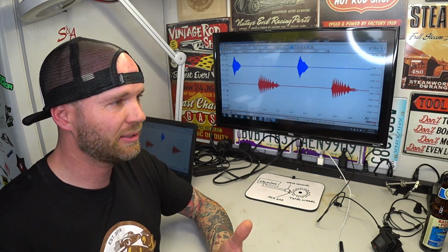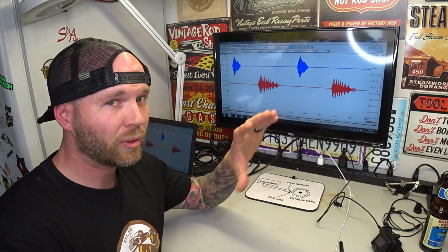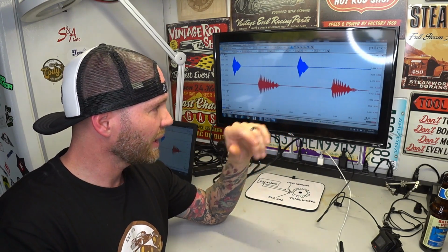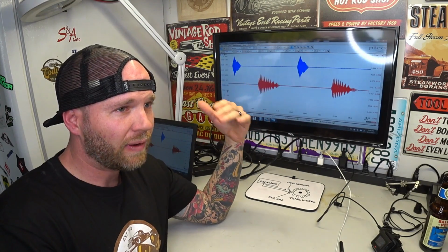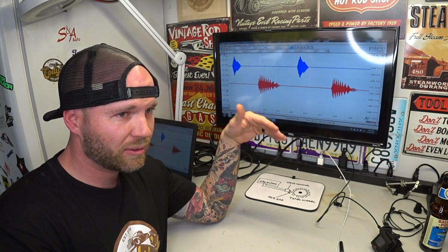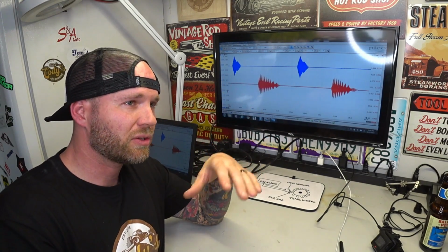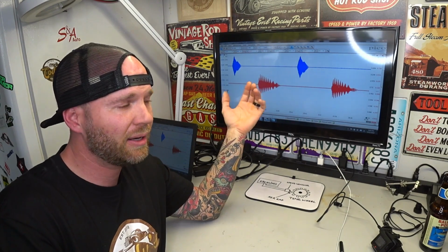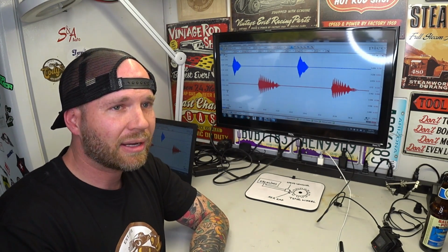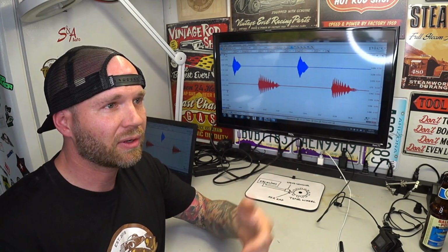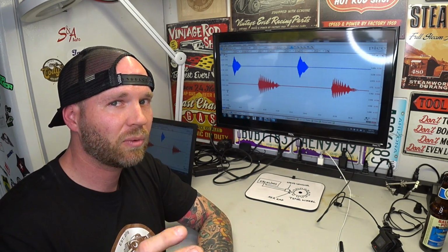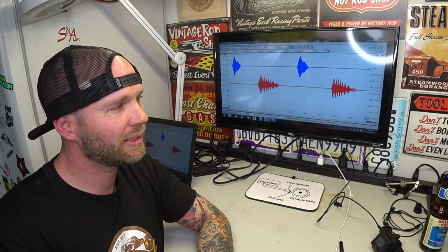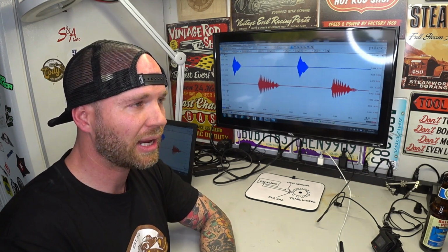It's like a crank sensor. You go directly to a crank sensor and you see, you know, the 0 to 5 volt square waveform. You're not going to find that on a scan tool. There's no PID for that. I mean, you may have an RPM PID, but that's not telling you anything. That's telling you if there's RPM, but that's not telling you exactly what that sensor is doing. And that's the importance of a scope. I mean, it's having a scan tool diagnosing vehicles.